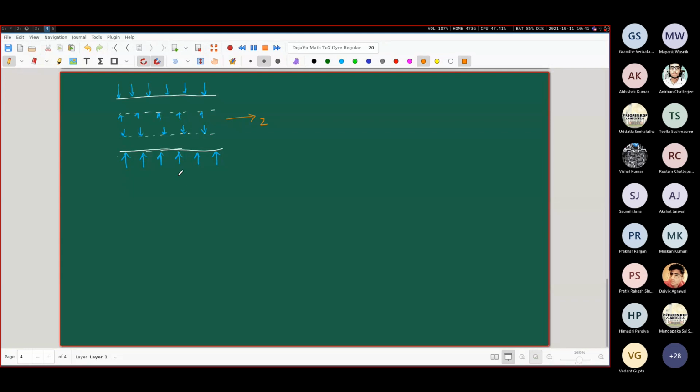So along the z direction, there is no non-uniformity in the pressure. It is perfectly uniform along the z direction. Furthermore, another requirement of plane strain is that there should not be any component of the external force along the z direction. And that is also satisfied here directly because here the pressure is acting perfectly in the radial manner. Okay, in the radial direction it is taking place.